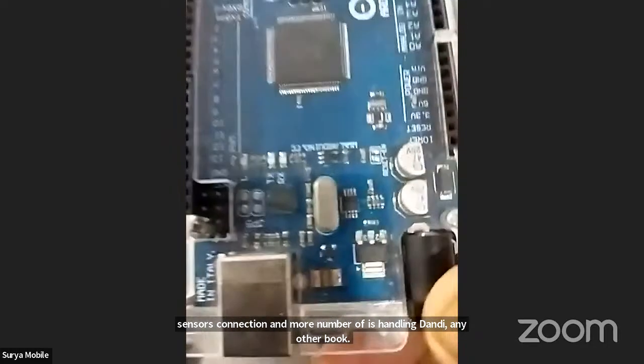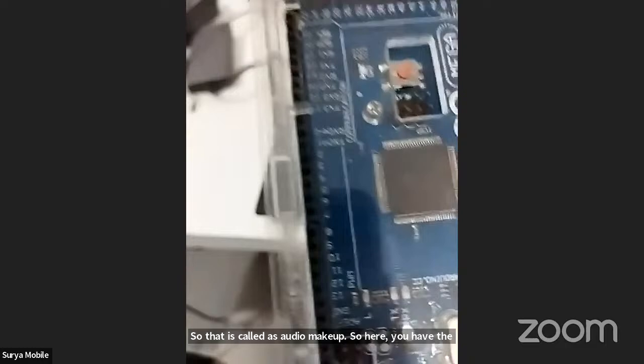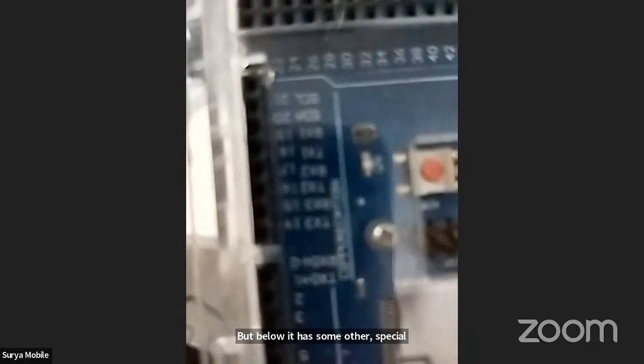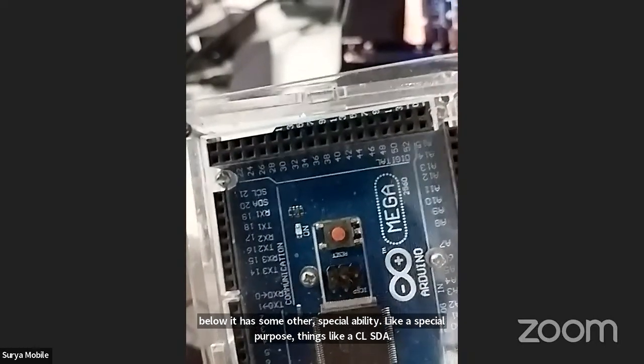Here you have the same functionality, but you will have more digital input output pins along with some special pins. Starting from here, you have the same Arduino UNO pins, 0 to 13 digital input output pins. Below it has special purpose pins like SCL, SDA, and extra digital pins.